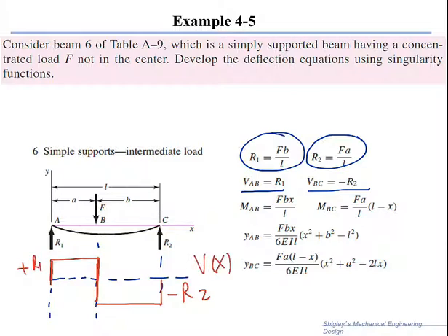This is the actual applied force diagram, and therefore for us to find the deflections, we can do the integrations of V to obtain theta, and then do another integration to obtain the displacement.